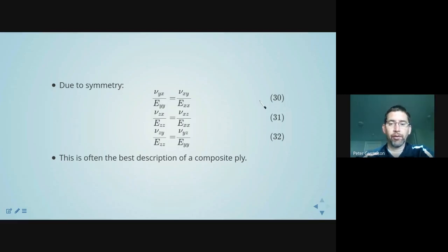And as I said, this is typical of a long fiber reinforced composite material. These materials are very broadly used now in aerospace engineering. Every fighter jet in the current 5th generation is predominantly composite material in its primary structures, at least those that are not associated with the engine and the thrust that's generated. The really high temperature stuff still tends to be high temperature metals as opposed to carbon fiber. But most of the remainder of the structure is made out of carbon fiber or similar.